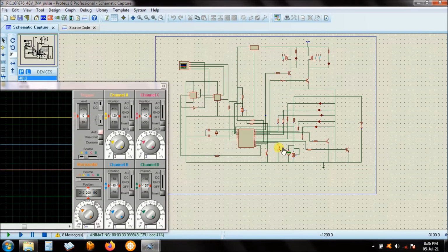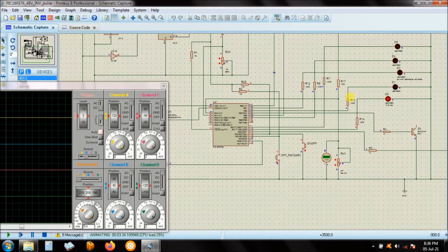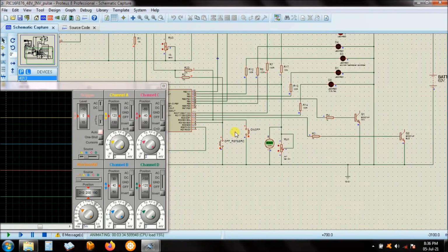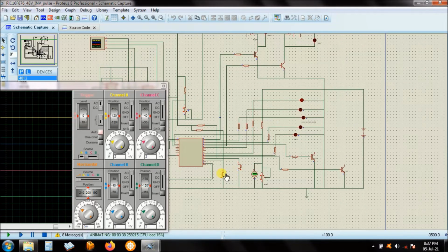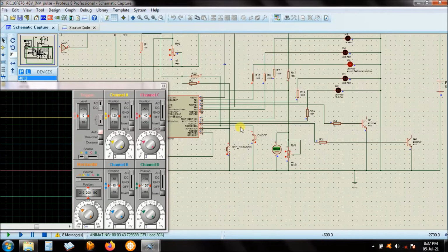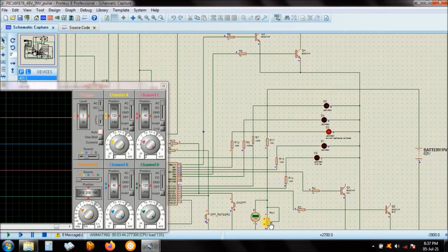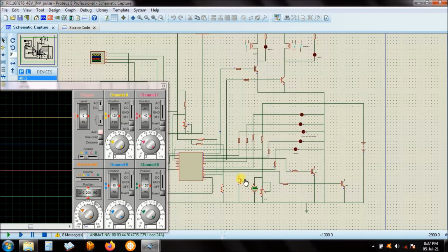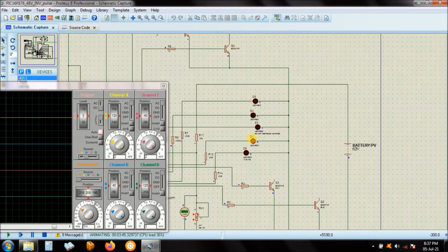and then switch it on there. Right, let's see if it is in the battery mode. The battery mode is this one. Okay, the voltage must be right for the inverter to start, for the inverter to be reset. You can't reset when the supply voltage is out. Okay, so let's change to battery mode. It's low. Now it's in battery mode. So in battery mode, the voltage levels here are different. So when I start it in battery mode, you see the LEDs, they just go on.